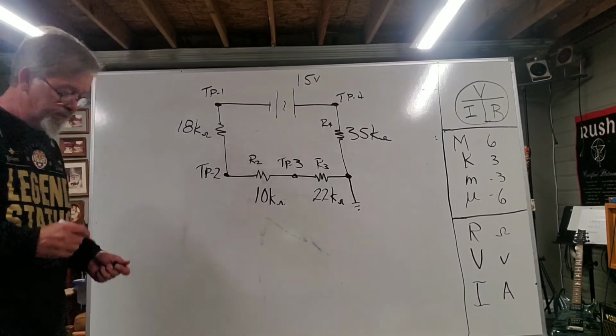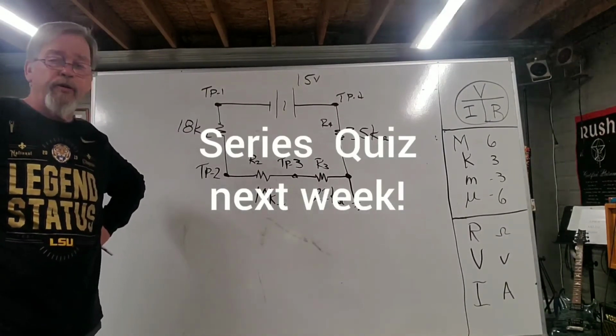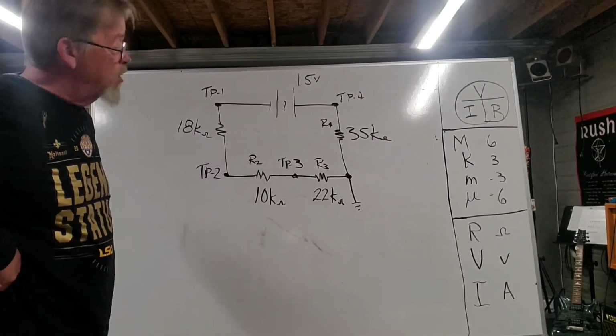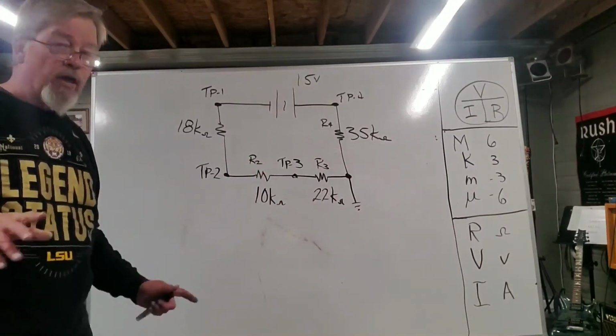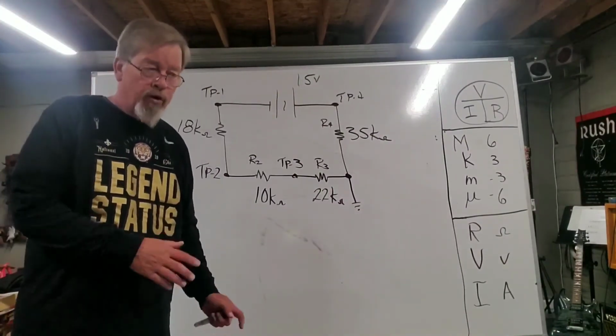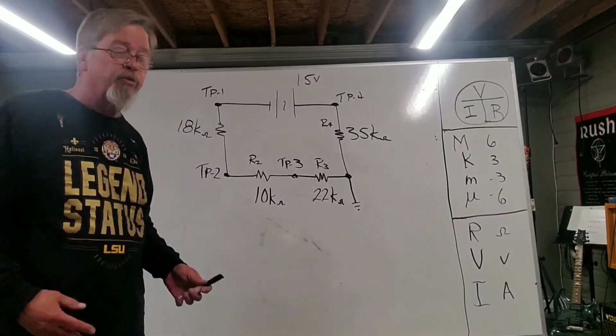Okay, there's your third one. So I'm thinking we're going to need to have a quiz next week, get this series circuit. The quiz is going to simply consist of one series analysis problem with test points. So study all that up. Make sure you remember the common points within the series circuit. Current's the same, you add up resistors, and the voltage divides and adds back up to the total voltage.